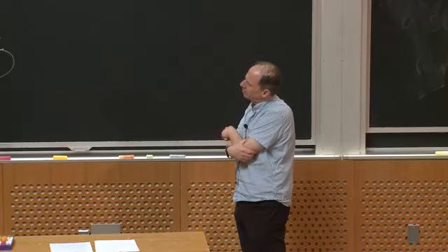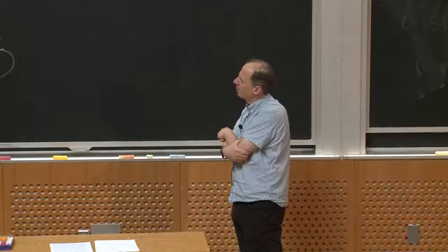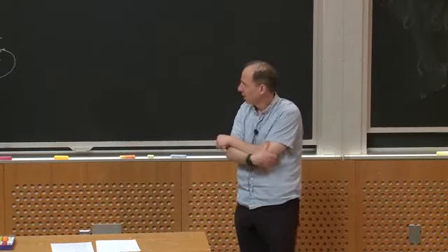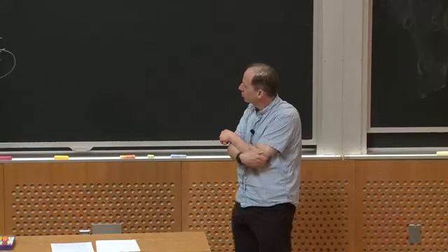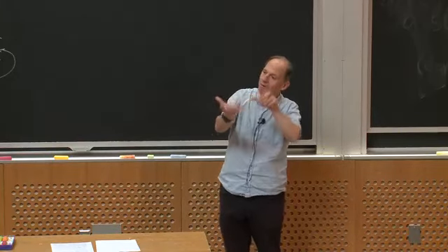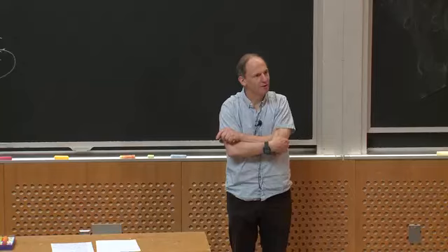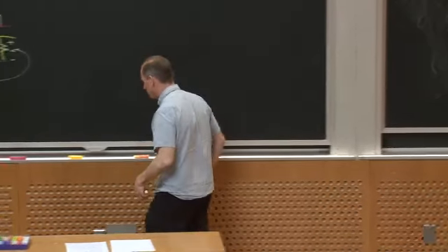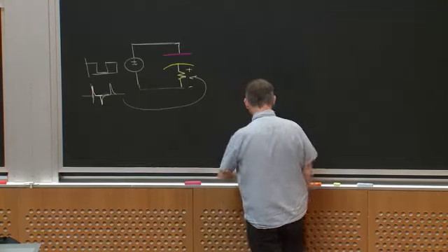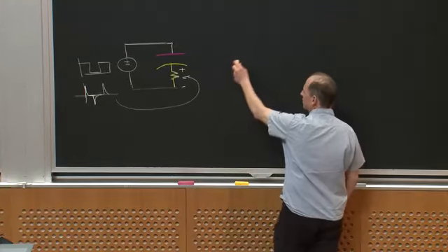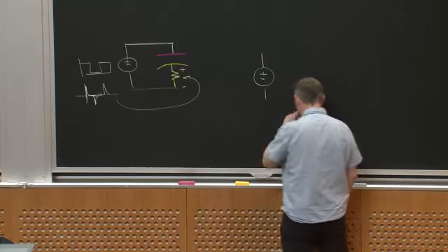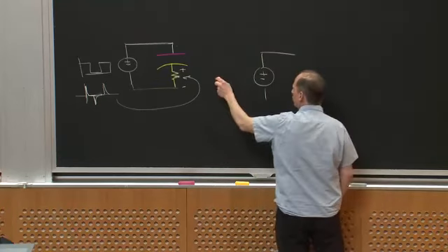Well, another thing I could do is start to get smart about where those components are and what I put in between them, okay? One thing I could do is put in what's known as a Faraday shield, or lay out my circuit so I effectively get a Faraday shield. What's a Faraday shield? Suppose I did this instead. I have my switching node, right?